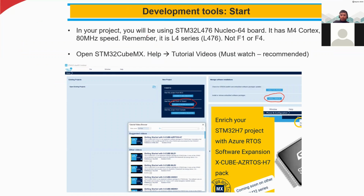In your project, you will be using STM32L476. I repeat again, a Nucleo 64 board. So it has M4 Cortex, and it has 80 megahertz clock speed. And remember, this is L4 series, not F1 or F4. So we will also see F1 based, but basically everything is the same. But if you are really going to work with the hardware, you have to have the correct libraries.